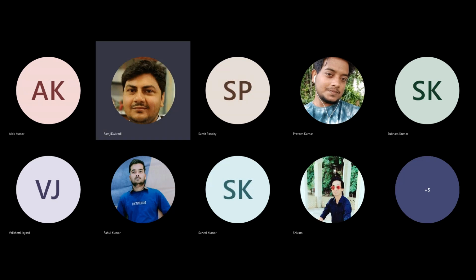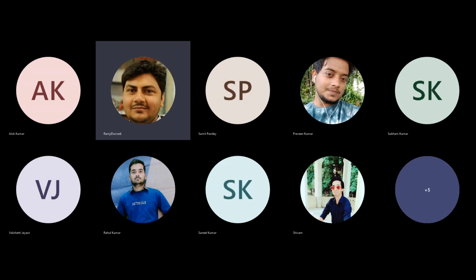The requirement to remove random error is there because you get an inconsistent solution, and we have seen that in our previous lecture. That means we have got 5 observations, we have to find one unknown, and we have 9 ways by which we can find x, and for every case x is getting a different value. So we have seen the inconsistency in the solution. The reason is simple, because you have randomness in your data set. Your observations contain errors, because of which you are getting different x.